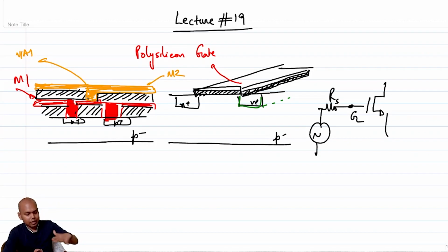I'll have to note that the gate is somewhere connected. Note that the gate is on M1, right? And if I have to connect something to the gate which is at the other end, not sitting next to the transistor, then obviously I'll have to make a physical connection from this gate to that. And because I have to cross over multiple flyovers, I have to develop a contact or a via that connects my M1 to probably an M2, correct?